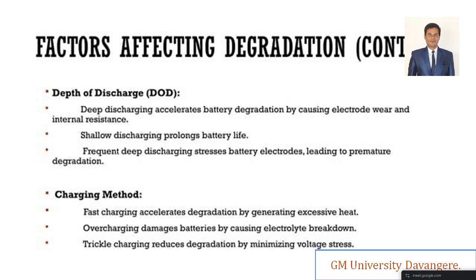I gave the example of your work assignment also, so that it is very clear to you. The point is shallow discharging prolongs the life of batteries. And if you think about frequent deep discharging, it puts stress on the batteries, on the electrodes. That may lead to premature capacity fade and power fade, so that leads to premature degradation.